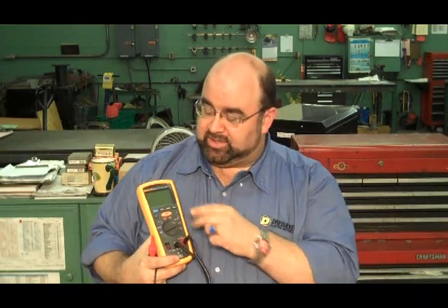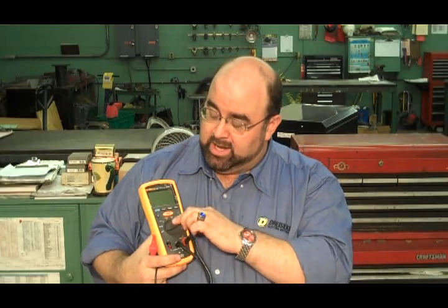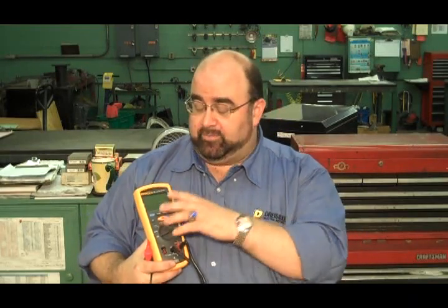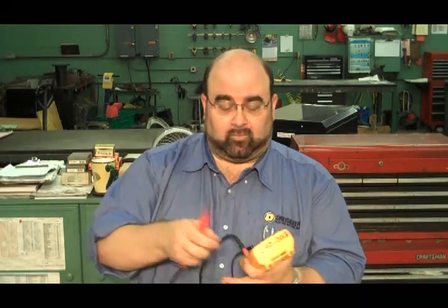The other method that's used is called a Megger, or insulation resistance tester. There's a multiple of different types. This particular one is a handheld unit, and this handheld unit basically has a test capability and can do insulation resistance at 500 and 1000 volts. This one will also take an ohm reading. Now these are our standard technologies.